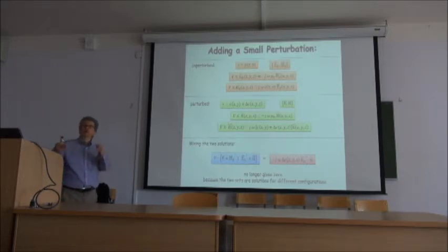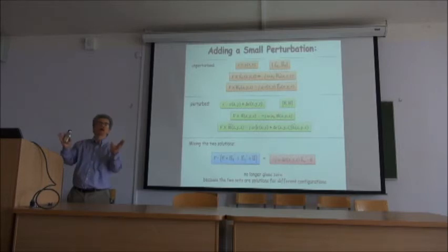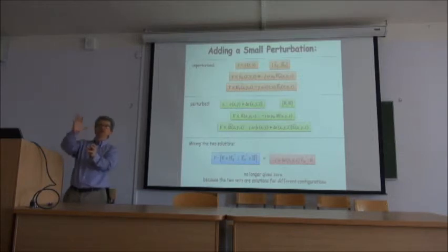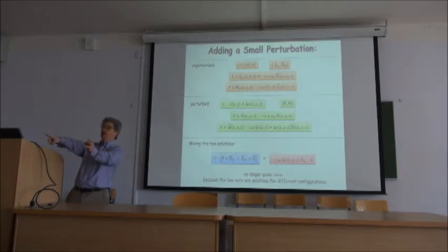And let me be concrete here. What is that perturbation? It can be of many kinds. It can be that I have a waveguide here, and I found those solutions by looking at the refractive index here and on the surrounding. And I bring another waveguide here. The perturbation can be another waveguide that gets closer. It's changing the refractive index in this region.